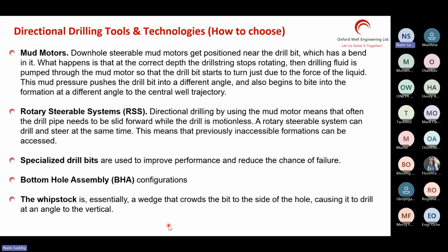Technology, what technology are they going to be using? If they are going to be using a mud motor, it can do all the profiles, very, very popular. RSS tools, most of them cannot do certain dog legs. Certain dog legs, you don't want to plan. If they are going to be using an RSS tool, don't put in dog legs that are very difficult for RSS.